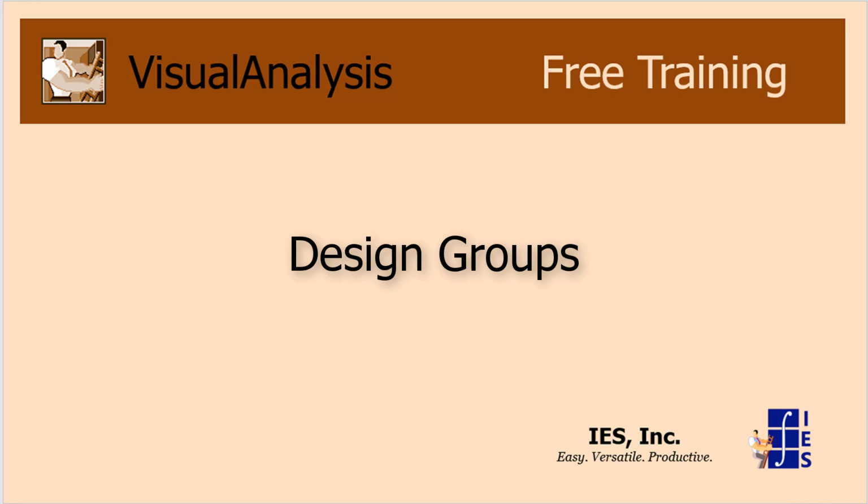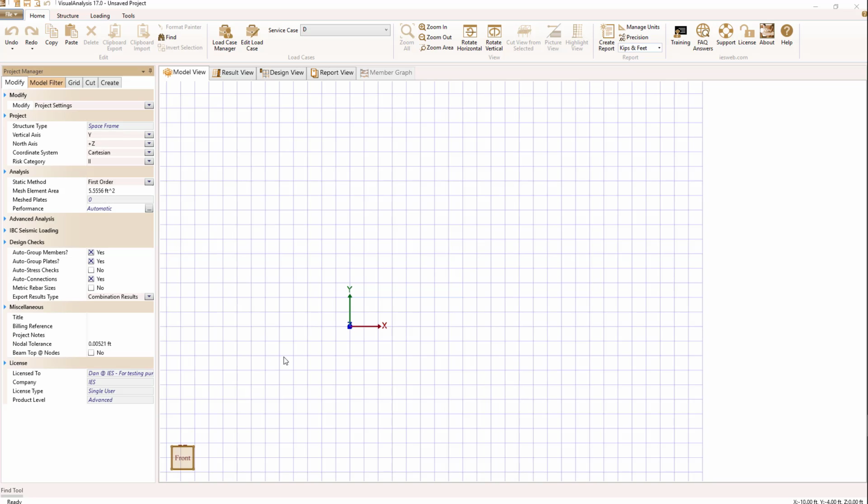Let's talk about member design in VisualAnalysis. The basic member design unit is what's called the design group. This represents a group of members which share the same design parameters, and in the end, we'll end up with the same design shape. By default, design groups get created automatically.